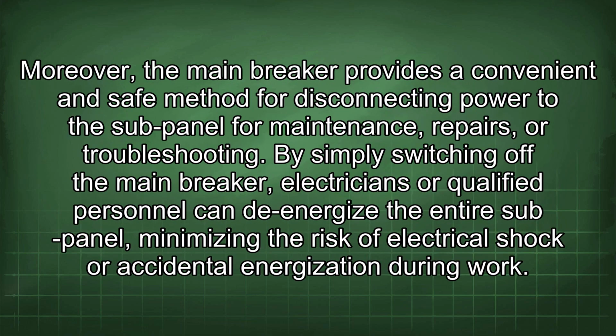Moreover, the main breaker provides a convenient and safe method for disconnecting power to the subpanel for maintenance, repairs, or troubleshooting. By simply switching off the main breaker, electricians or qualified personnel can de-energize the entire subpanel, minimizing the risk of electrical shock or accidental energization during work.